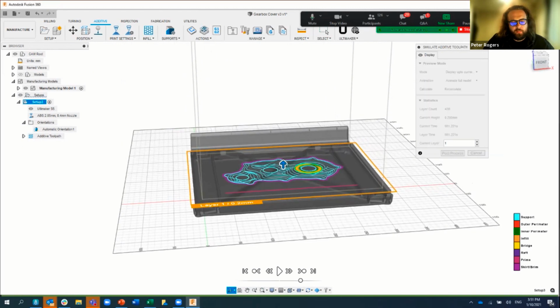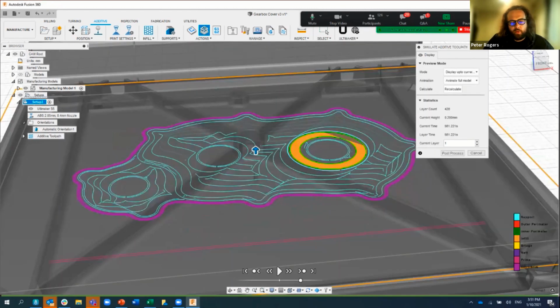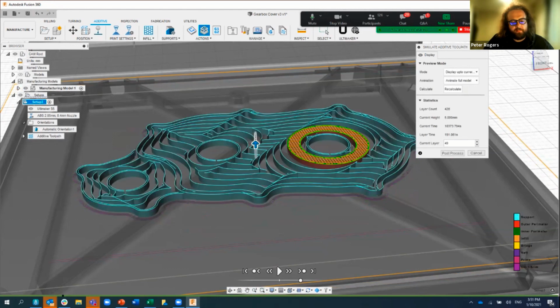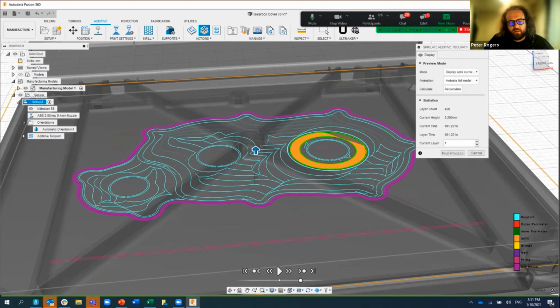With the 3D printing technology, again, it's a layer by layer process. You can see that there are different things happening within this design, and the different color coordination of what each of these toolpaths is doing. It's creating a skirt to help it adhere to the build plate. You've got the blue sections that are going to be the supports, and the orange sections being the geometry.